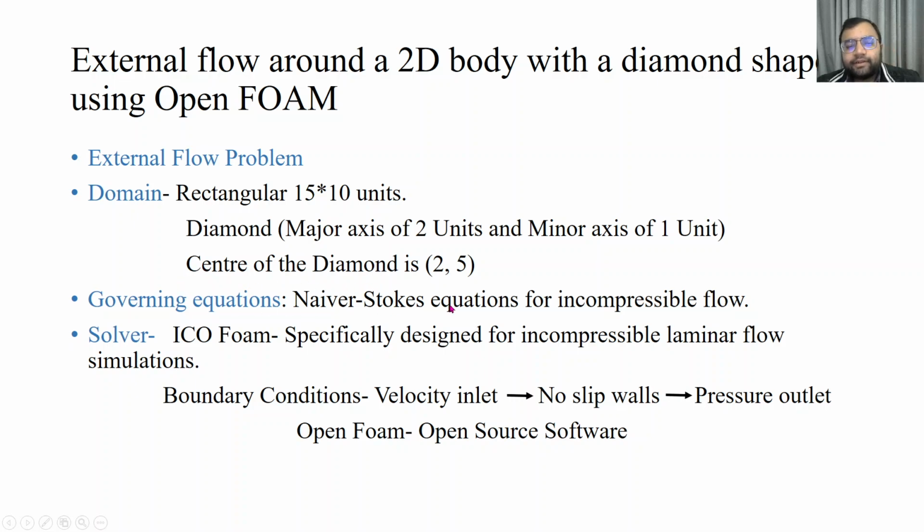The governing differential equations that we are using in this flow problem are the continuity equation and Navier-Stokes equation for incompressible flows, and the solver that we will use for our simulation problem is icoFoam, which is specifically designed for incompressible laminar flow problems. The boundary conditions in this problem are velocity inlet, walls at no slip condition, and the pressure outlet condition.